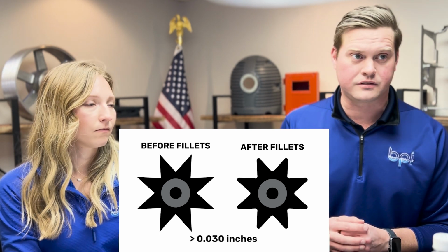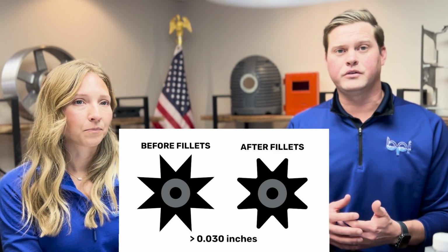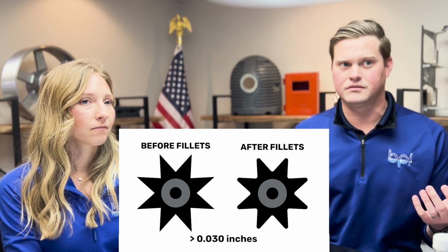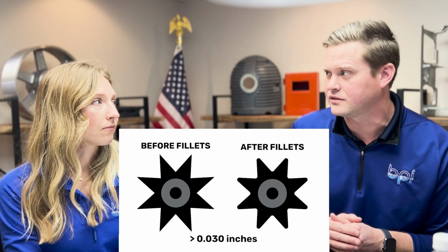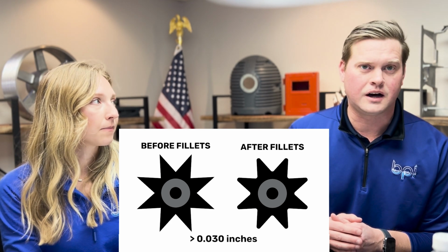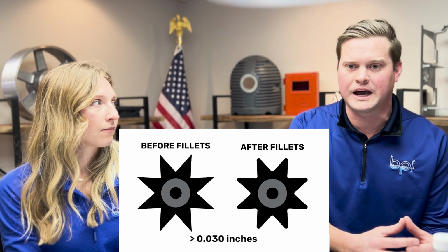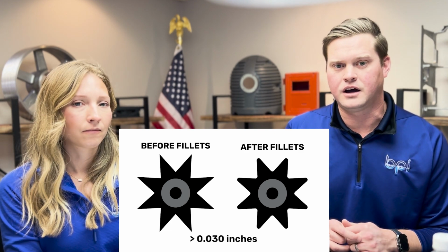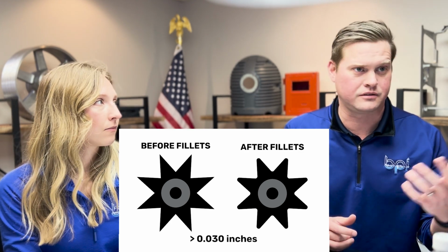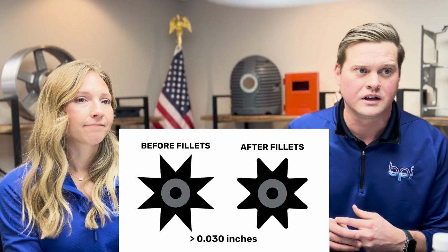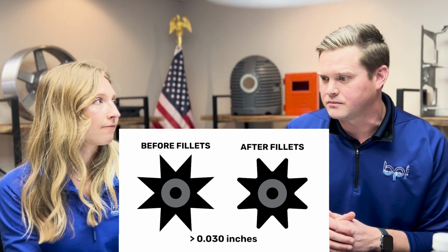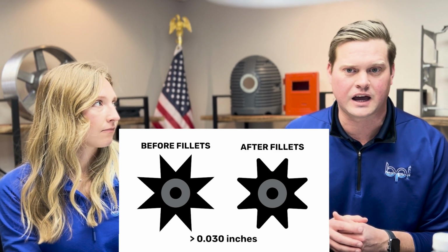You touched earlier on surface finish. But really on the casting process side of things, sharp corners can cause a number of issues. Yeah. So again, we want to make sure we're casting good product coming out rather than having to scrap parts because it's cracking or there are high stress areas, or, as you mentioned, cold spots creating tearing in the casting.